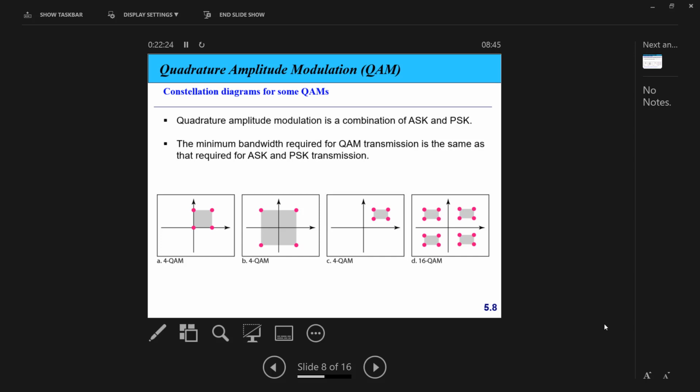This is one element. All these bits are sent constant in one element. So r equals 4, which means I have 16 levels, and now we have 16 combinations in the same signal element. So I have 16 points. Each point is represented by a certain phase and certain amplitude. Okay, but this is a general case for QAM. Right. Is it easy to plot this figure?